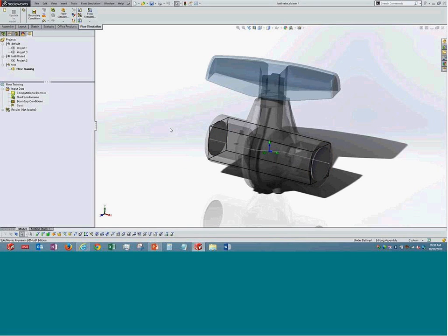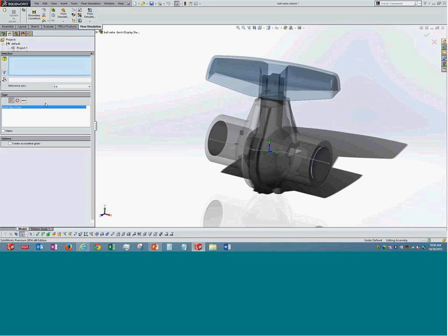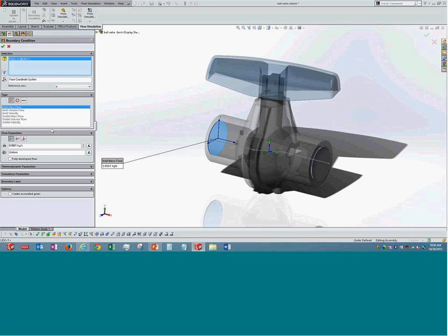Now, say the fluid is entering through this face. We can specify the mass flow, volume flow, or we can specify the pressure, or whichever condition that we want, and those can be input over here. So for the mass flow rate, over here it is 0.000, that is the default value. I'll change it to say 0.7 kg per second, based on the tutorial. So don't ask me where I got this value. It is more of an example, but you need to know this value in detail.